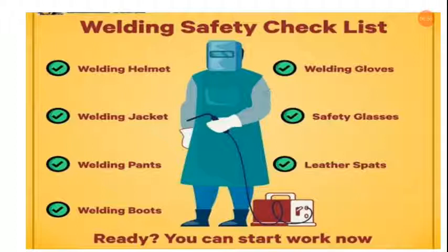Plastic or fiber insulation on the electrode holder prevents contact with electrically hot metal and parts inside. Always inspect the electrode holder before turning the welder on. Replace the holder if it is damaged. Don't try to repair it unless replacement parts are at hand. A damaged electrode cable should be replaced or at minimum repaired using electrical tape. If the cable has been repaired, check that the tape is secure before turning the welder on.